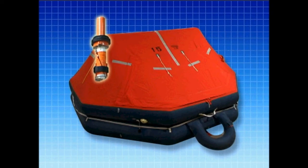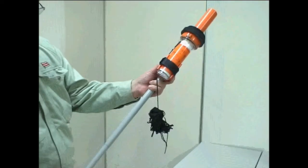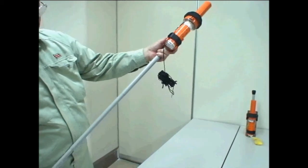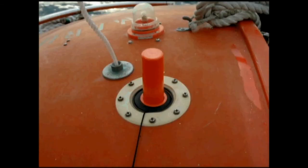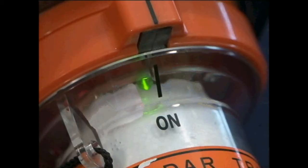In a life raft, the SART should be located as high above sea level as possible, and in such a position that the red LED light can be seen from the cabin. The SART signal is received from the radome's horizontal direction, so make sure that objects such as radar reflectors are not obstructing the upper part of SART. The SART battery is capable of 96 hours of uninterrupted use, so its power should not be switched off until rescue is complete.